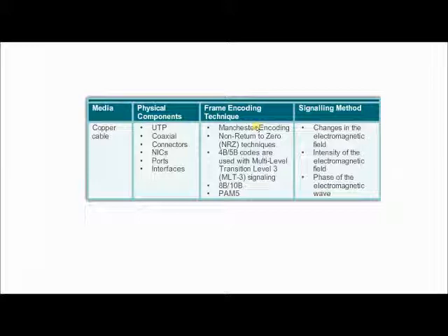Then there's encoding, which is a method to convert data bits into a code pattern. This pattern can be recognized by the sender and the receiver as zeros and ones. Two examples of common methods are the Manchester encoding, where a 0 is represented by a high to low voltage and the 1s are represented from low to high voltage. There's also the non-return to zero method, where a 0 is represented by one level of voltage and the 1 by another level of voltage on the medium.